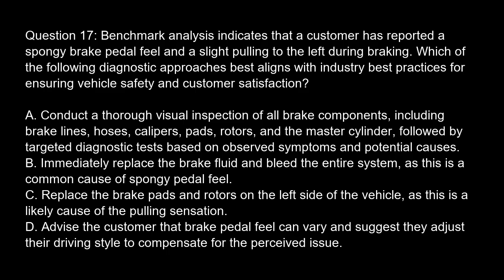Question 17. Benchmark analysis indicates that a customer has reported a spongy brake pedal feel and a slight pulling to the left during braking. Which of the following diagnostic approaches best aligns with industry best practices for ensuring vehicle safety and customer satisfaction? Option A. Conduct a thorough visual inspection of all brake components, including brake lines, hoses, calipers, pads, rotors, and the master cylinder, followed by targeted diagnostic tests based on observed symptoms and potential causes.